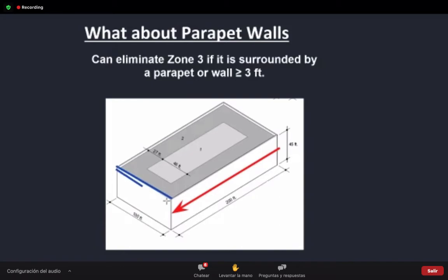So there's my gutter edge, my drip edge, if you will, whatever you have there. And we have parapet walls around the 3 other sides of this building. So in these 2 corners on the blue area right here, this is where we're going to need that L shape. Hopefully this makes sense to you guys in the audience. And the only reason we don't need it, once again, like Wally was saying on the top, is because the walls are greater than 3 feet high.